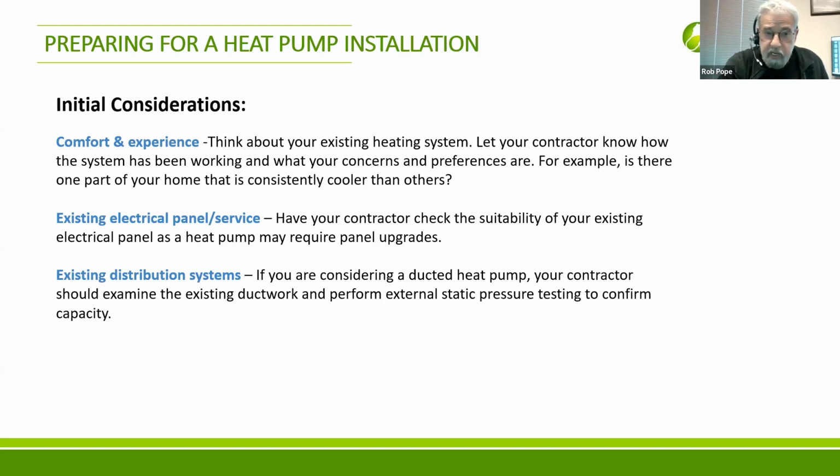So that's one thing. On the air quality, yeah, you're right. There's a lot of issues with indoor air quality, especially when the house gets tight. A tight home needs air moving. It's not just about replacing stale air with fresh air from outside. It's about managing all the air in the building, because the HRV is only injecting a certain amount of fresh air into a fixed volume, which is much larger than the volume of air the HRV is moving.